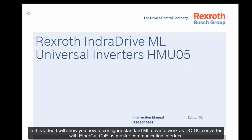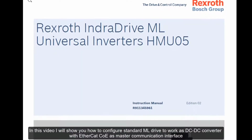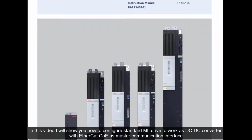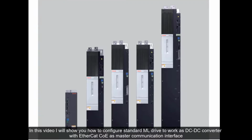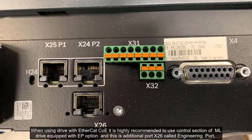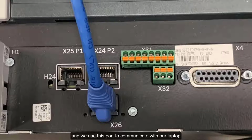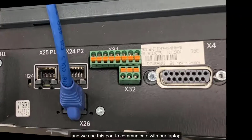In this video, I will show you how to configure standard ML drive to work as DC-DC converter with EtherCAT CoE as master communication interface. When using drive with EtherCAT CoE, it is highly recommended to use control section of ML drive equipped with EP option, and this is additional port X26 called engineering port. And we use this port to communicate with our laptop.